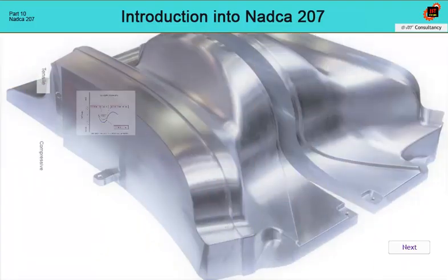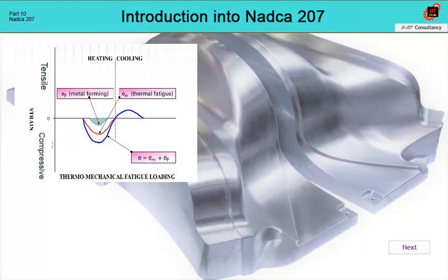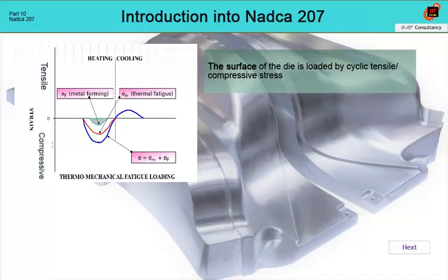First of all, it was necessary to define which properties affect this service life. It is known that the surface of a mold during die casting is subjected to alternating cyclic stress with regular alternation of the tensile and compressive components.